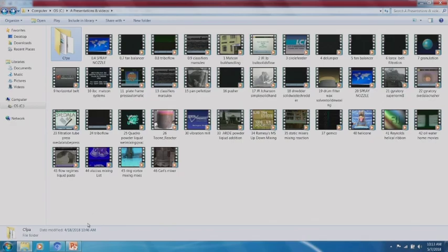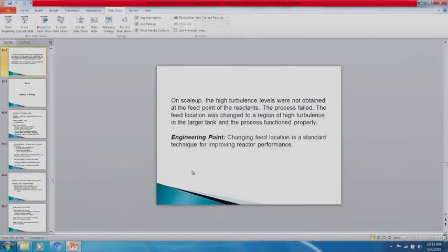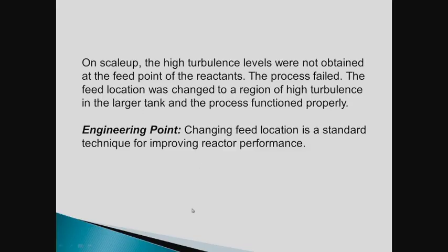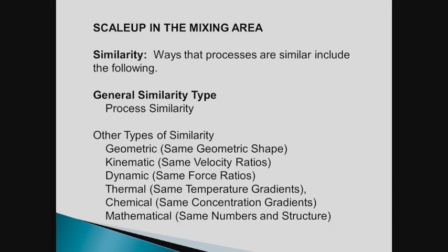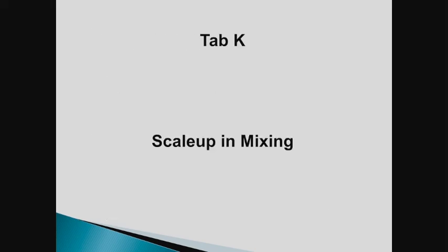Anyway, the video is about the RC1 reaction calorimeter. Basically in the video they show a poorly mixed system, a slurry reactor of some sort, and all the solids were at the tank bottom, and they were commenting that they were able to take great data that they could use in scale up. I seriously doubt that. Seriously doubt that.